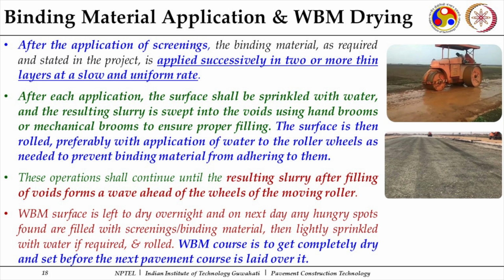Once the application of screenings is done, in certain cases binding material application is also required. There also, as I mentioned, the quantities of binder materials are already specified, that this much quantity of binding material has to be put over it. The binding material is applied as required per the codal documents, or many times as per the MORTH guidelines.